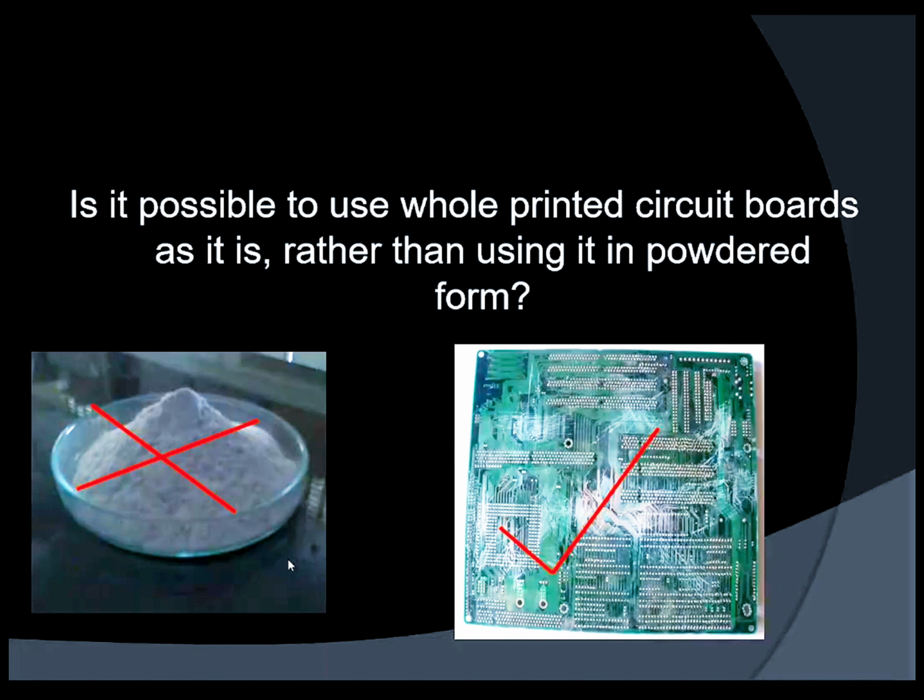So this is the process we have. Then here comes, as I said, the iron oxidizing bacterium, they are present over here. The iron oxidizing bacterium are oxidizing the iron, Fe2+. They are taking electrons from the ferrous, converting it into the ferric. Now it is the ferric which is oxidizing the copper, the bus line copper, which is in zero oxidation state. Whenever the ferric oxidizes the copper, the ferric itself gets reduced. Ferric gets reduced to ferrous.